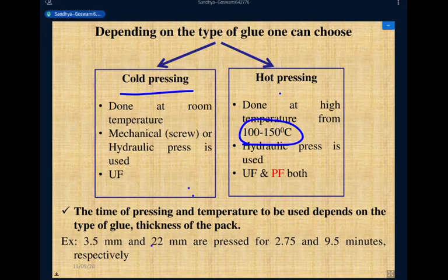But in case of hot press, your stacking will be different. There will be many compartments. Between each plate you keep one ply only, like the 3-plied construction you have made. If there are 10 plates, then between each two plates you keep one ply, right? So there is a difference in stacking. In cold press, all the plies can be stacked one over another, whereas in hot press, between two plates one has to put one ply.